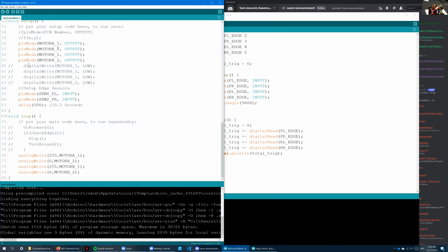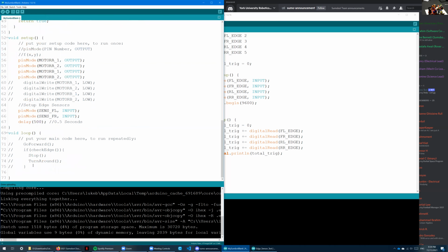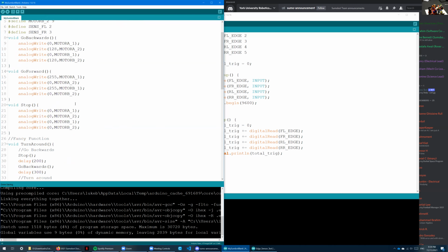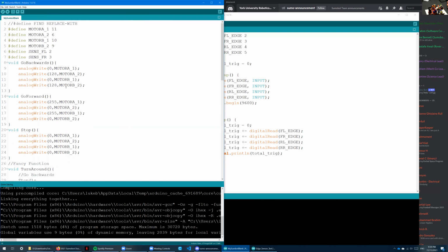Look up here, digital write. We define what pin number we're using, and then we define the value. Yeah, I did the value and then the motor pin. Oh, so you swapped the parameters. Yeah, I swapped the parameters. That's so annoying. It should have told you. Yeah, because there's no pin number that is higher than like 16 or something. So, wow, kind of offended, but I'll run with it. That means I need to change all these. No biggie, forever salty, but